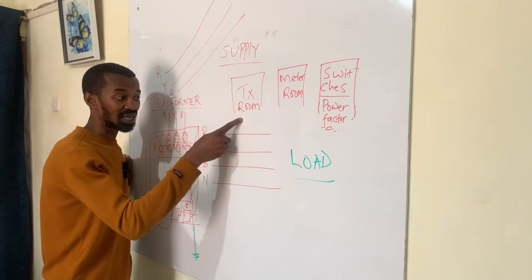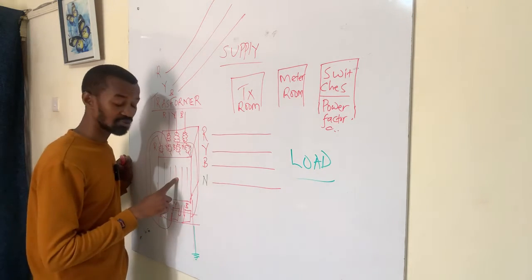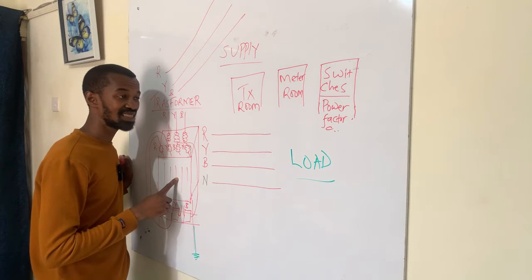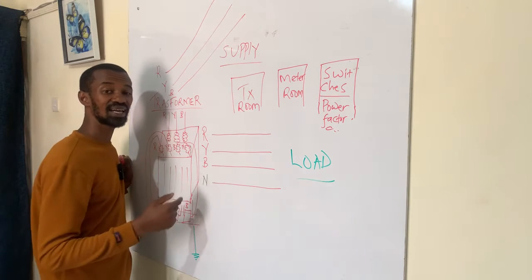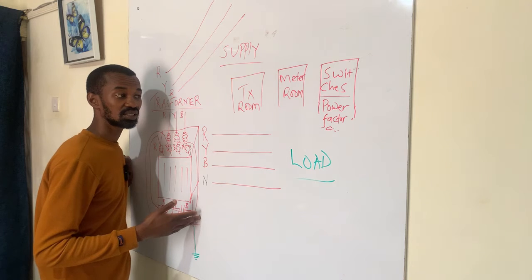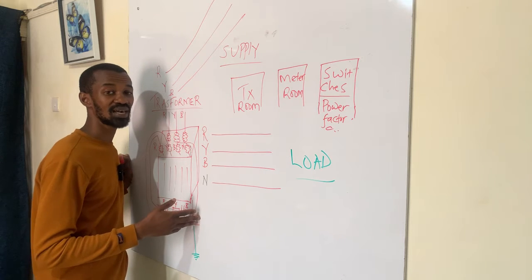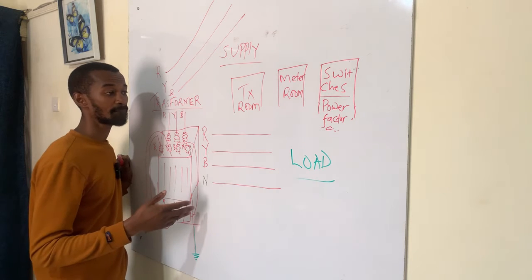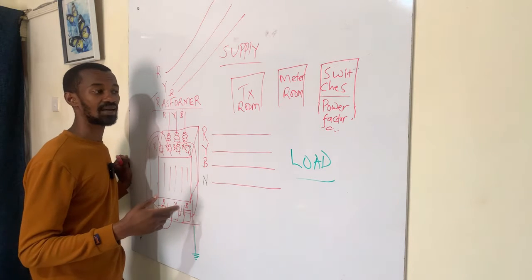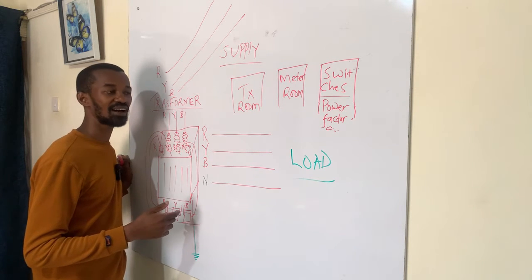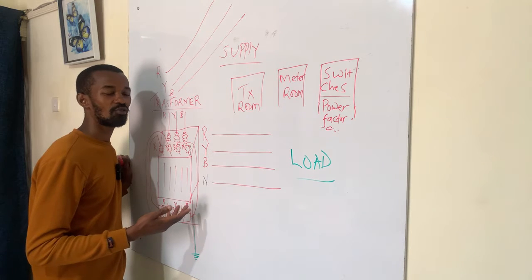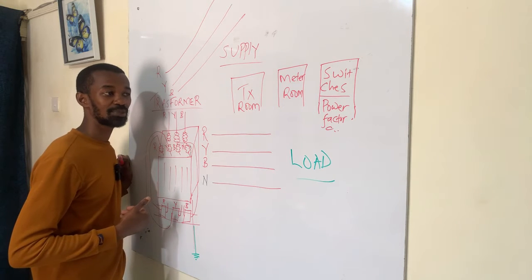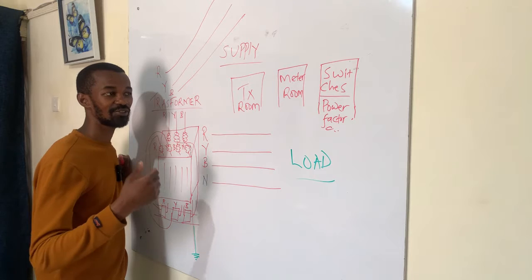You need to know that a transformer room has a transformer that will be sitting in there. And so how do you design even the walls? What are the materials that you're using there, considering that you need to ensure that your transformer does not overheat in there, gets enough supply of air for cooling purposes, especially if your client has a heavy load.